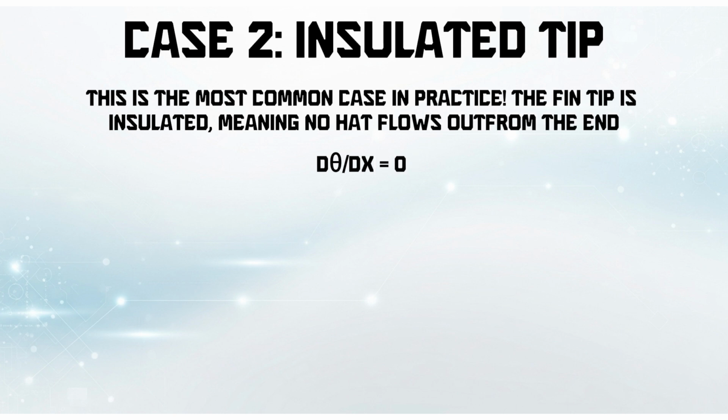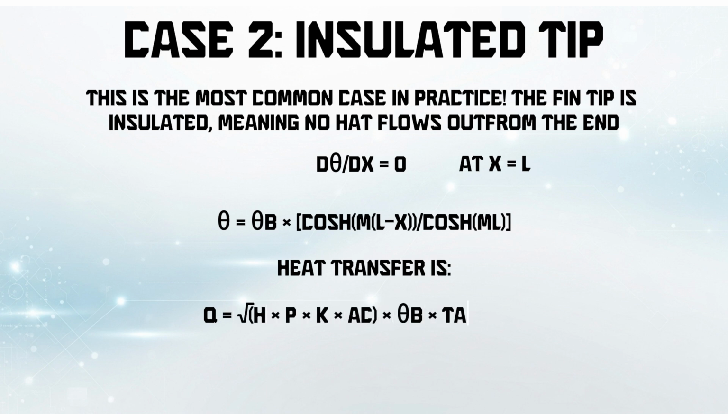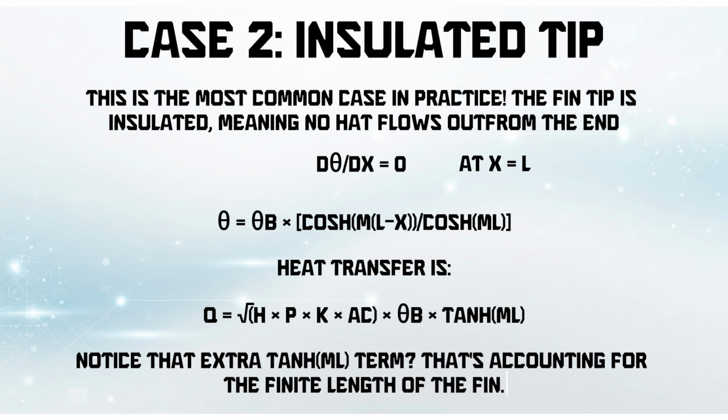Mathematically, dθ/dx equals 0 at x equals L. θ equals θb times cosh m(L minus x) over cosh mL. The heat transfer is Q equals root of h times P times k times Ac times θb times tanh mL. Notice that extra tanh mL term there. That's accounting for the finite length of the fin.